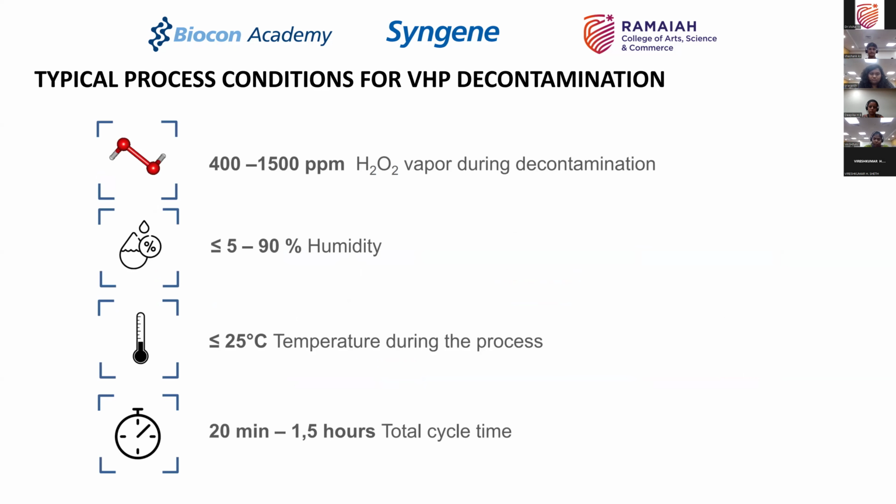Okay. Now, we will take VHP decontamination here as an example for validation, and I will take you through some of the steps which are there. The reason for taking VHP decontamination is that it is the most widely used decontamination agent in the industry today. Dosage rates are between 400 to 1500 ppm.